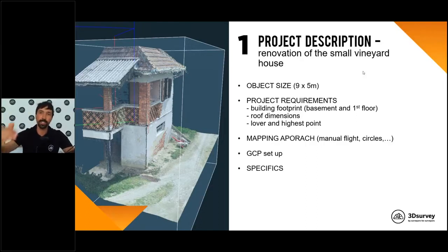I started with the grid mission at 40 meters, my first circle at 35 meters, then 5 meters lower at 30 meters, 25, 20, and so on. I tried to connect all the images together to get the greatest model out of it. At the end, I was flying at 5 meters above the terrain, or even less, because my phone images were triggered from 1.5 or 2 meter height, and I'd like to connect those two data sets together.